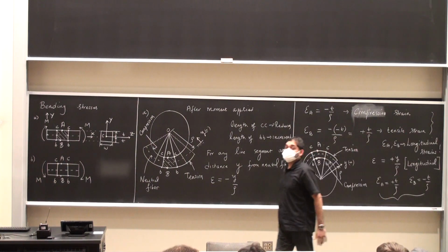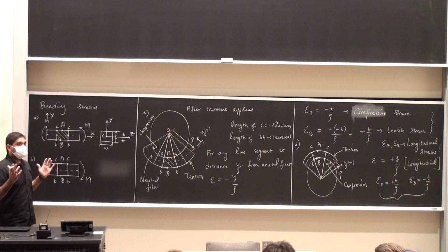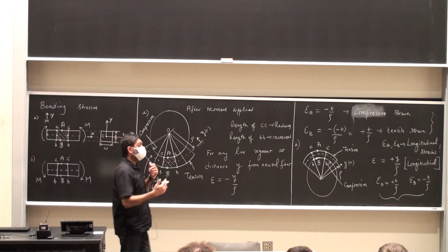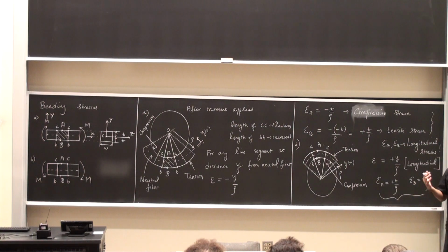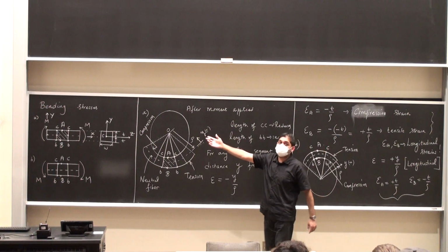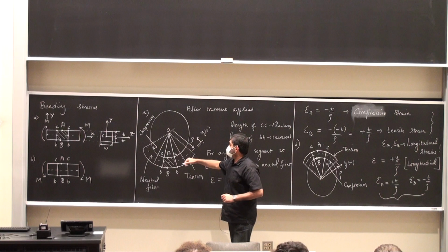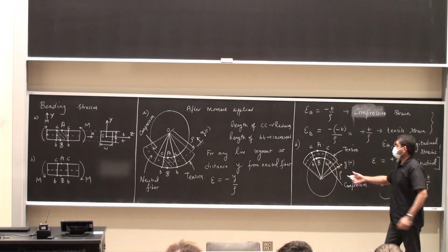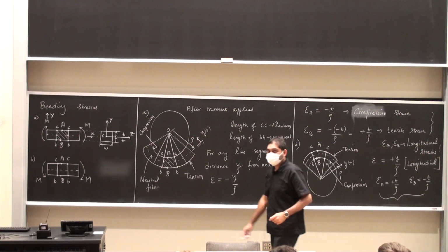But I want you to visualize these two hypothetical cylinders. Okay, every time you see a bending problem, look at the way the moments are acting. After you draw the bending moment diagram, you'll figure out if the moments are in the positive sign sense or the negative sign convention sense. And then you picture this hypothetically in your head. If they are in accordance with the positive sign convention, this is the state of affairs in terms of the strains. If not, you go to this one here. Any questions, please? So far.